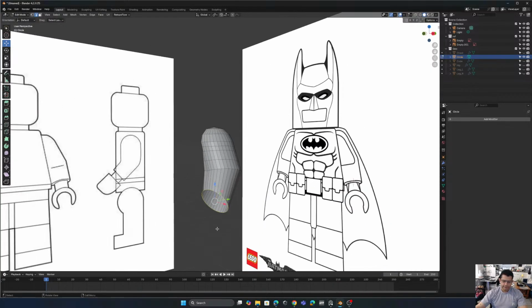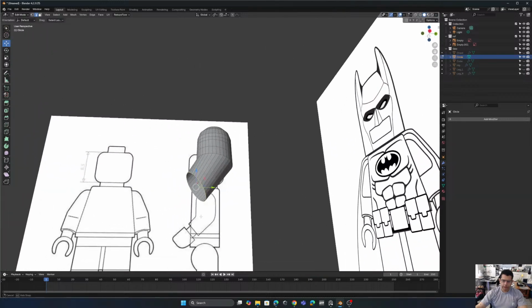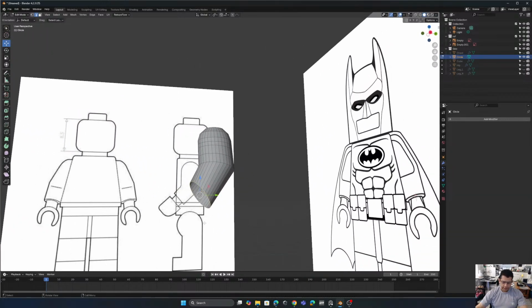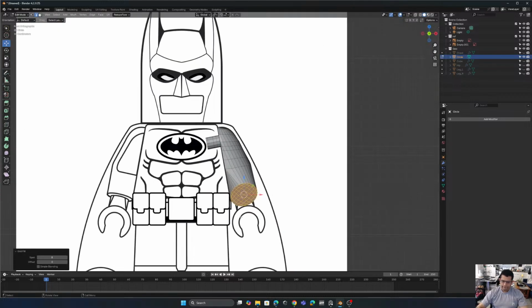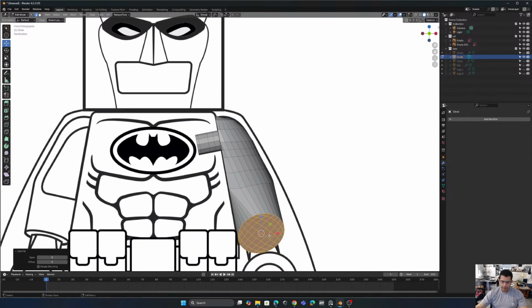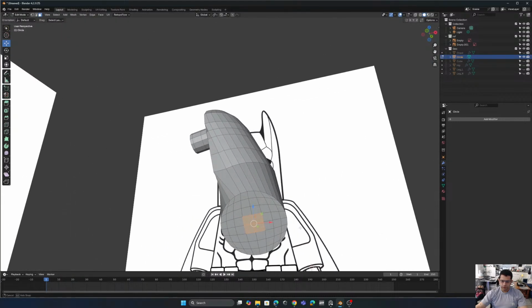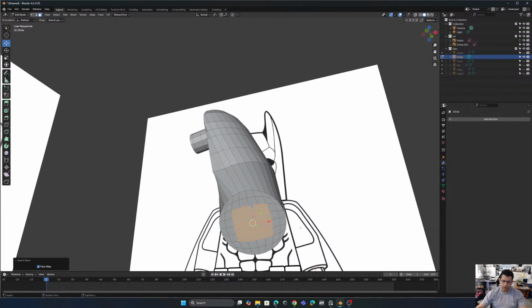Alt click, and we're gonna select all the edge loop. Then F3, grid fill. Now we could offset this a little bit to keep everything in the center, so much better. Now we select these 4 faces. 3 to select face mode. We select those 4 faces. Control plus to increase our selection.